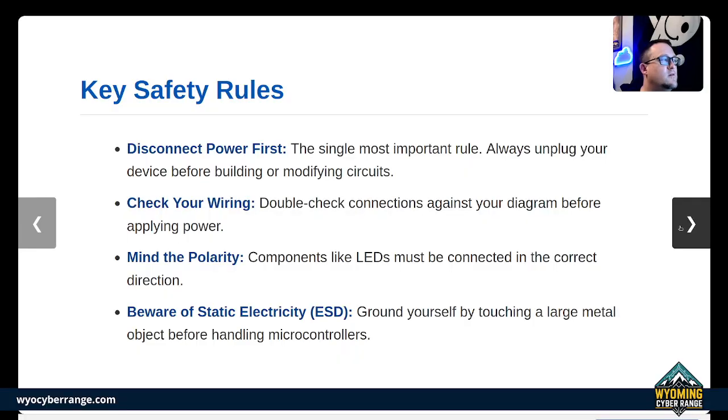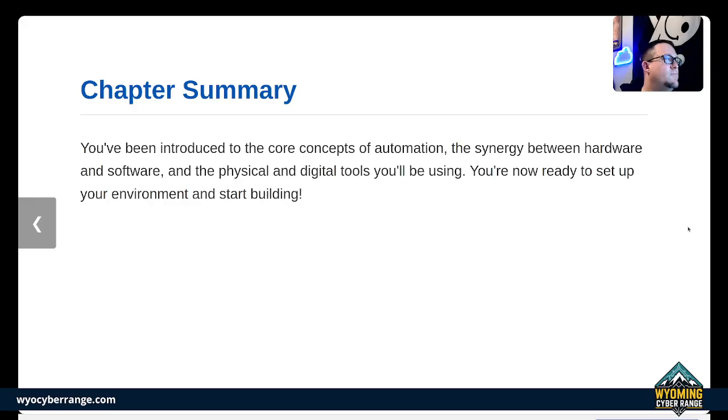So, disconnect your power first, check. Check your wiring, okay. Mind the polarity. As we go through things, I will tell you about polarity, like LEDs must be connected in the correct direction, otherwise they just don't work. But the beauty of them is a lot of these devices won't be burnt out because you plug them in incorrectly, okay. And then lastly, as I said, no socks across the carpet because you're going to be shocking your devices. Key safety rules. All right, so that's chapter 1.